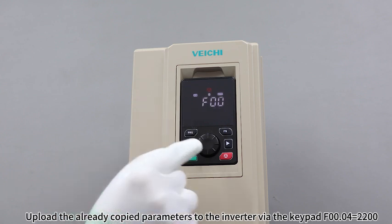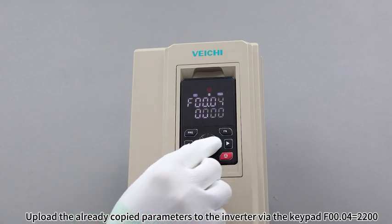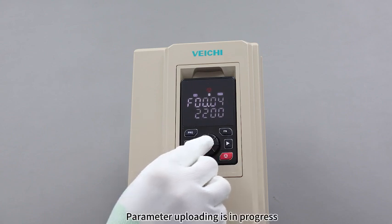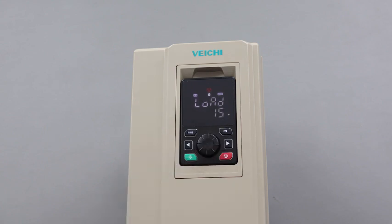Upload the already copied parameters to the inverter via the keypad, F00.04 equals 2200. Parameter uploading is in progress. Parameter uploading is complete.